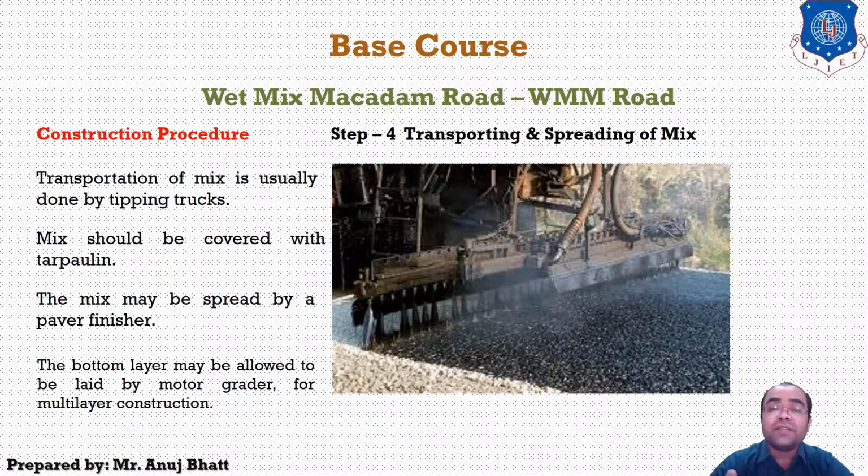After this procedure, the next step is transporting and spreading of the mix. Once the mix is prepared in the plant, it should be transported and then spread. The spreading should be done uniformly and evenly upon the prepared subbase and base course with the required quantities. Holding of the mix over a freshly compacted stretch is not permitted.